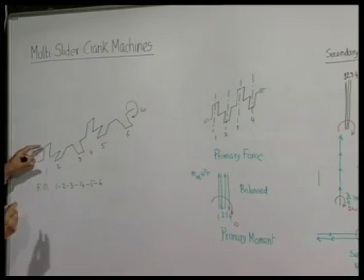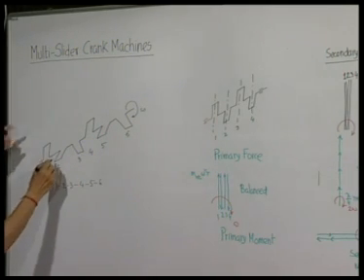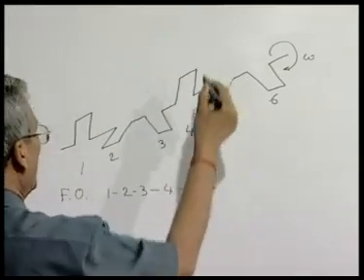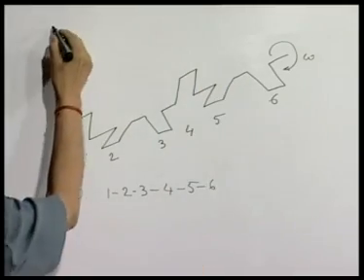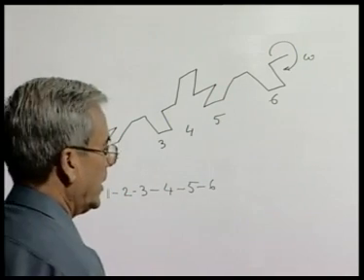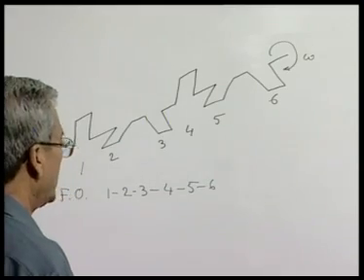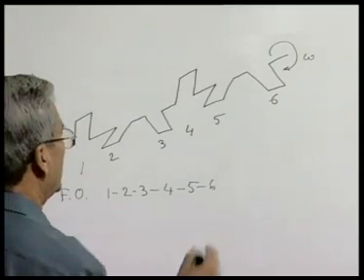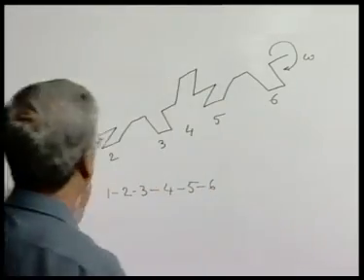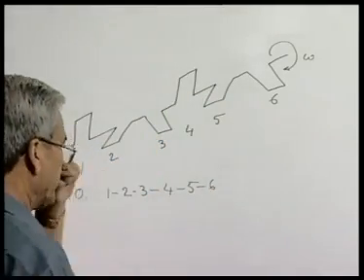So, first this fires because it is at the top, next comes 2, next comes 3, next comes 4, and so on. So, after every 120 degrees of rotation one firing takes place, and a total of 720 degrees, that means 4 pi, will be taken to make all the cylinders fire once.